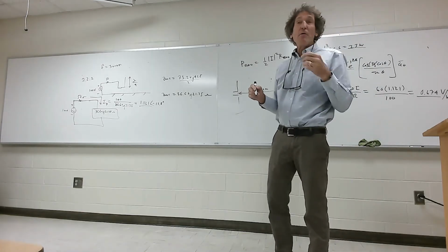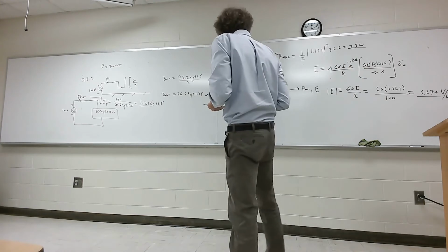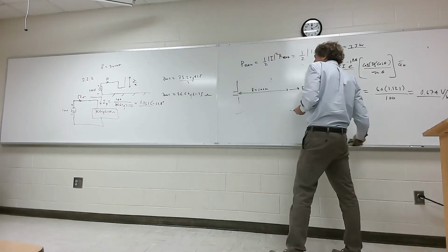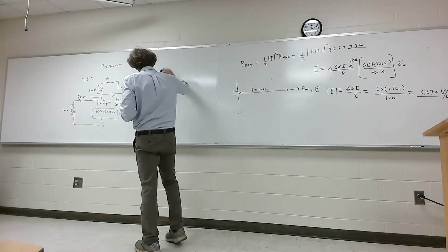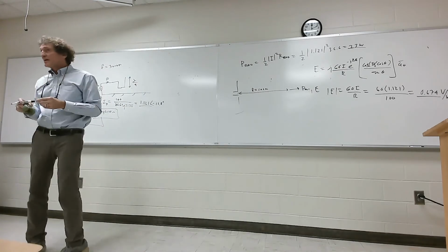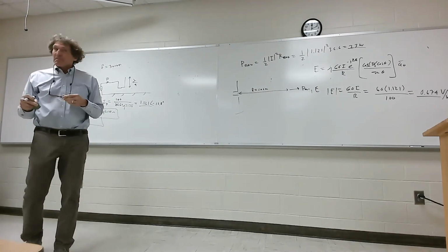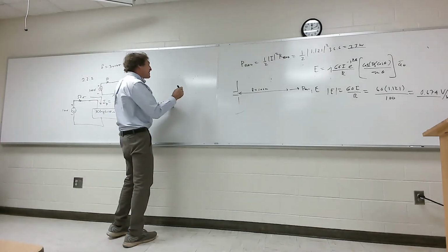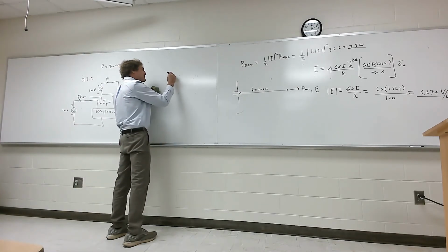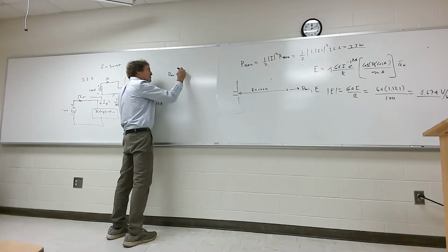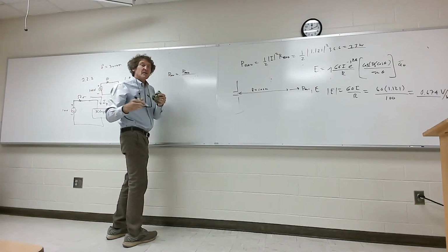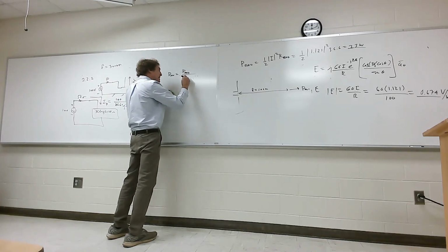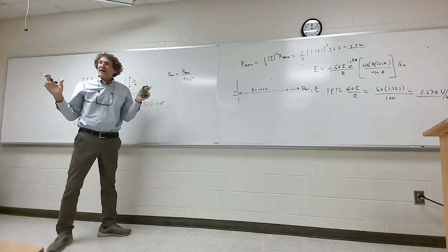Yes. All right, how else could we do it? This is the way I usually do it. Well, I would get the power density, right? How do I get the power density? The way I always get, if I want the average power density, what's the trick? I always take total radiated power, right? Total divided by, that's right, 4 pi r squared. Now that's the average power density.